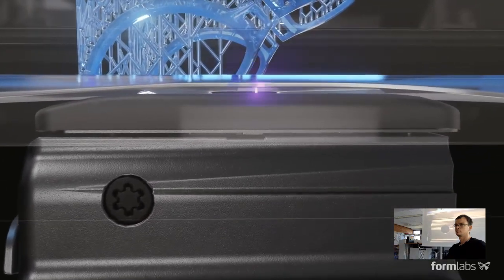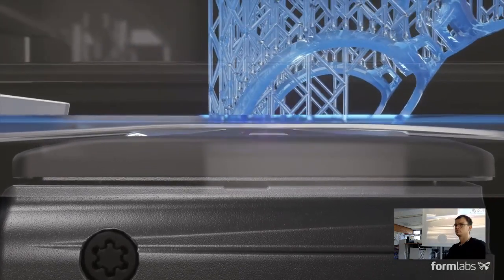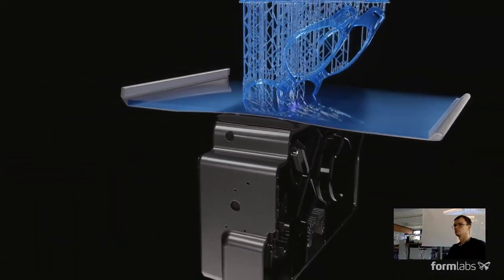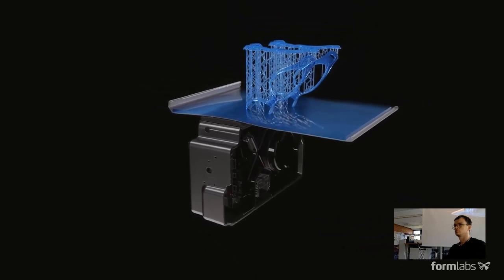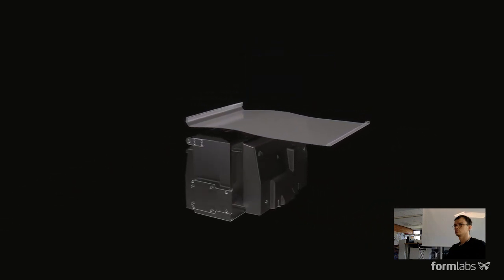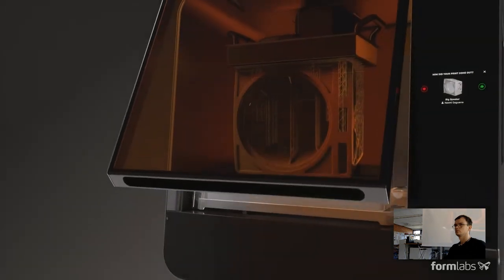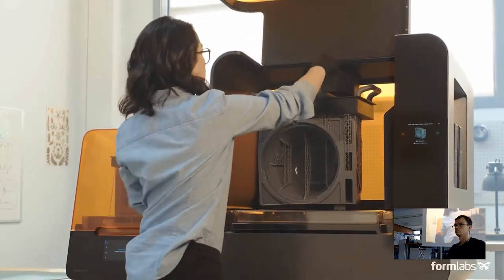A flexible tank reduces forces while printing for incredible surface finish with fewer supports, while the LPU provides precisely controlled linear illumination for accuracy and repeatability. Another advantage of LFS is that it works at scale. The Form 3L uses 2 staggered LPUs to offer 5 times the print volume. With twice the laser power, now you can print large parts fast.